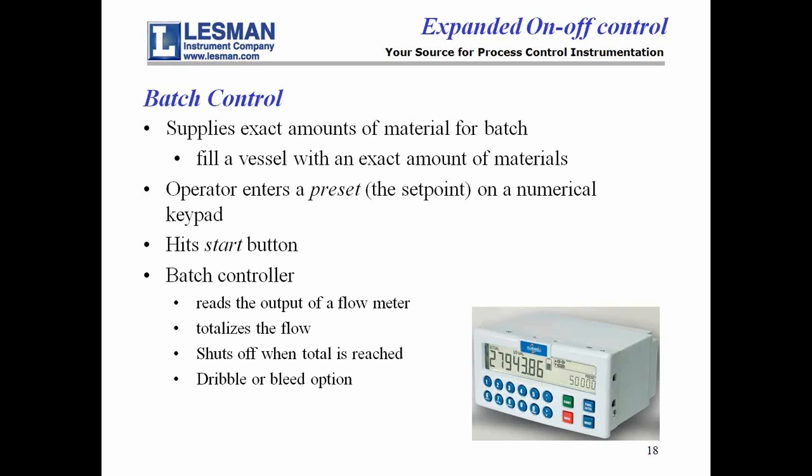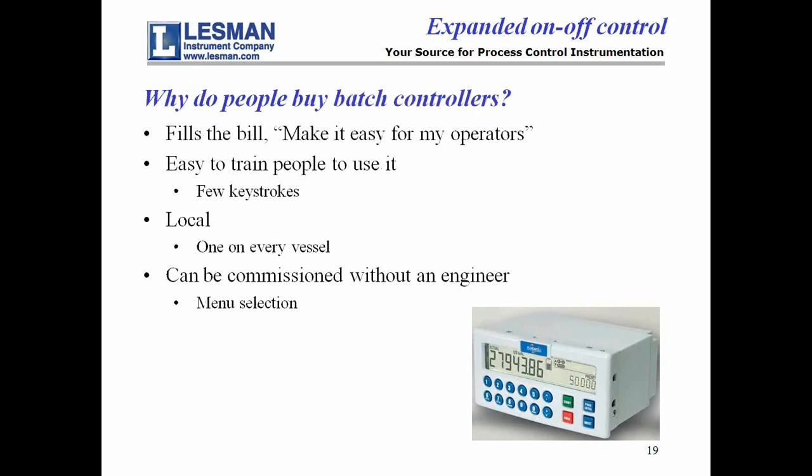Why do people buy batch controllers? Well, primarily because the thing we always hear is, make it easy for my operators. They want it easy to train the people because they want as few keystrokes as possible. They want it local. They want one on every vessel so that the operator can't confuse which controller goes where. You're not on an HMI screen picking different things. And they can be commissioned without having an engineer show up to do it. They're basic batch controllers in a box.